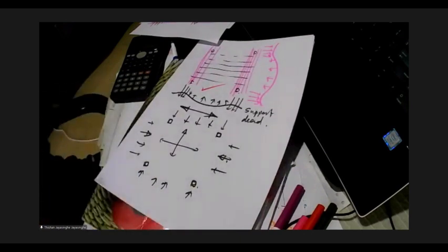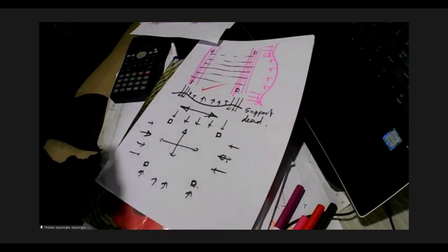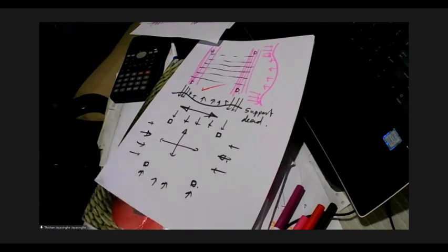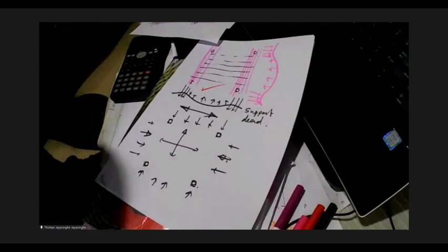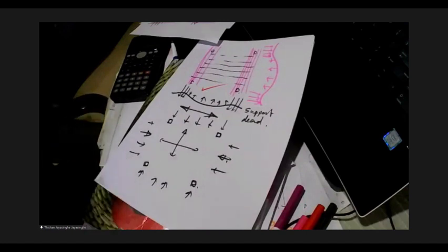So first we select a thickness, and then we arrange a set of cables in this one-way spanning system, and then we transfer the loads onto the strips, and then we provide a concentration of tendons in those strips, and then we can see whether the behavior is okay or not.